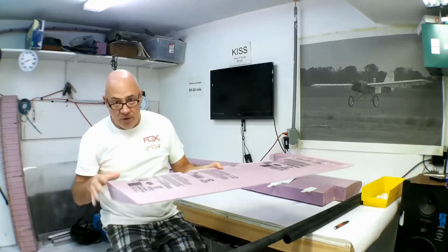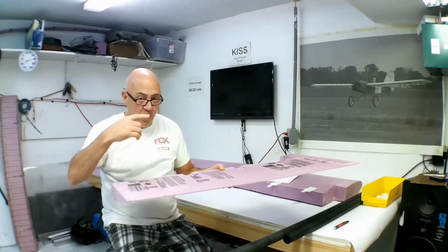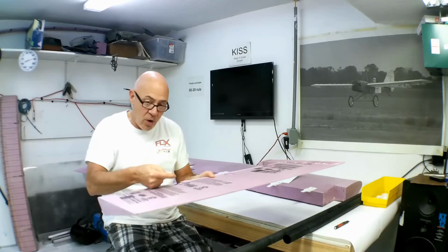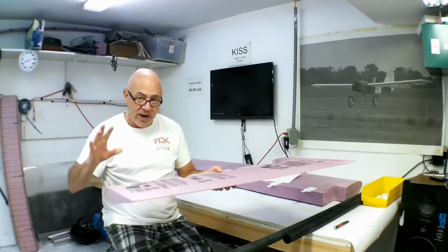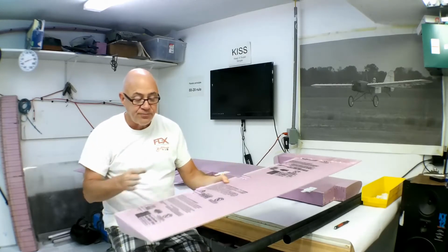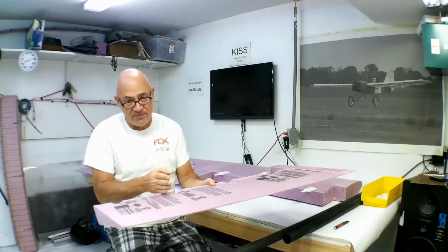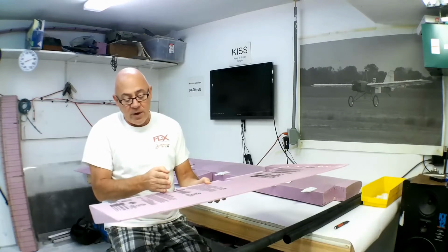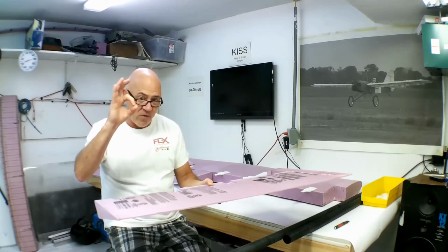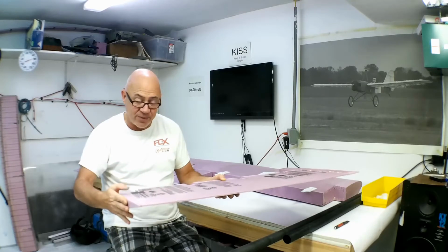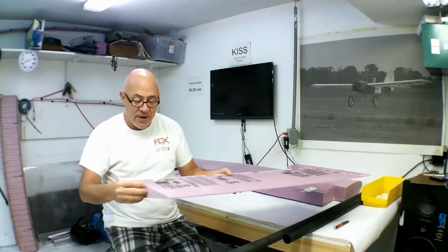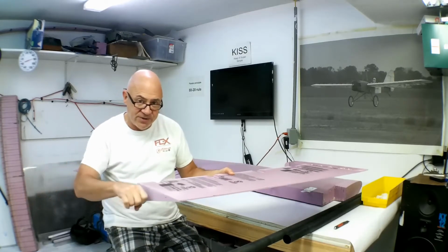If you are building a foam wing, you're going to hot wire the foam, and before you sheet it, you're going to cut a slice through it and put in a plywood rib that has a hole for where your socket goes in. So when I cut a wing out, I'll have an airfoil shape and an airfoil shape. I'll hot wire cut it out. I will cut the wing about 25%, 30% out. And then with the airfoil that I had here and there, I have a hole cut in that airfoil already. So I then slide the airfoil template on here, the template moves out here, put it here, and then I'll go down through the top and I will cut with hot wire the hole that the tube slides into.